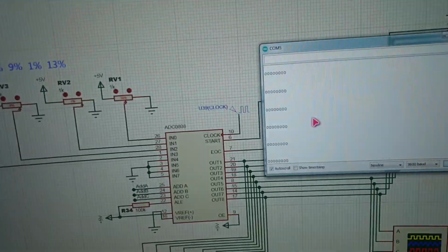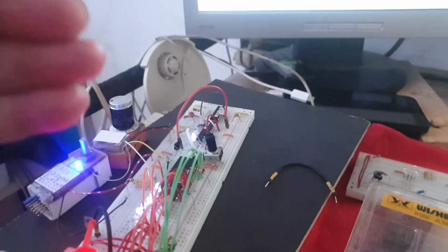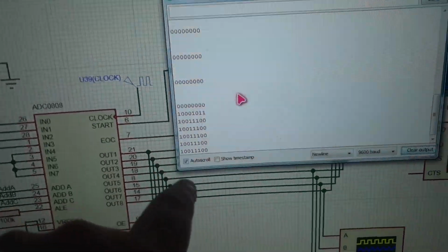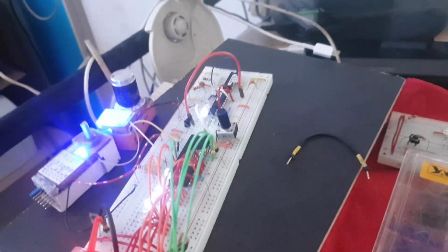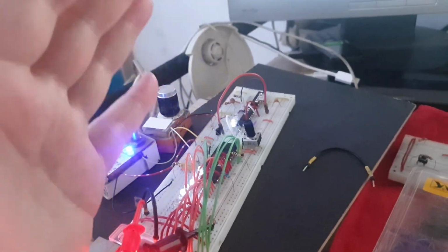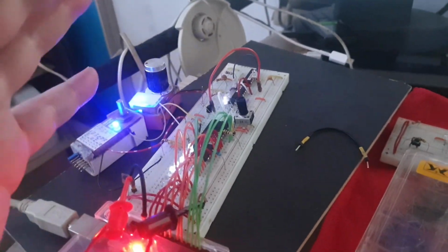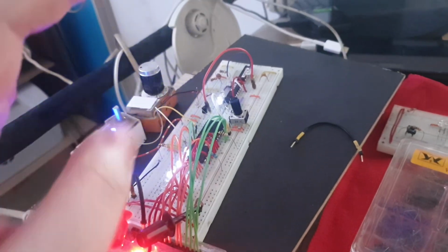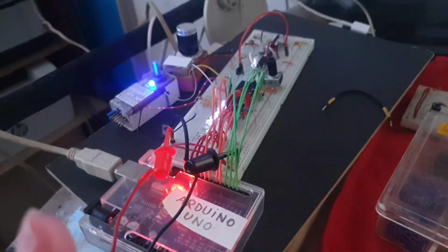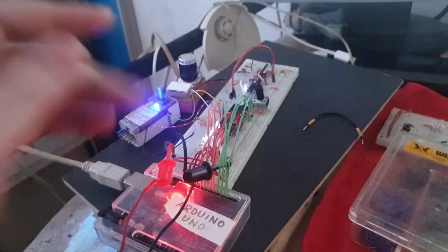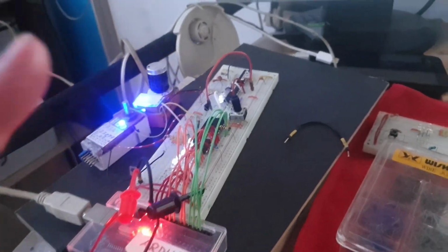And when I took it out, when I changed the potentiometer, all the LEDs started to light, and the serial monitor that I have here started to show things. And yeah, that resolved the problem. But expect errors, mostly from your inattention, because you cannot know everything at the same time. You have to do it step by step and figure it out step by step, like I did here myself. So this is it, the implementation in reality with Arduino, and it is working, and I absolutely love it.